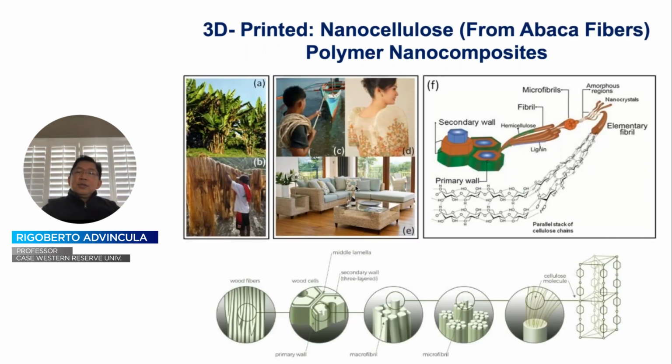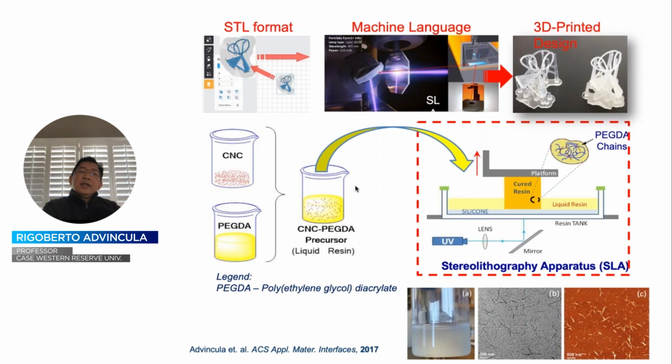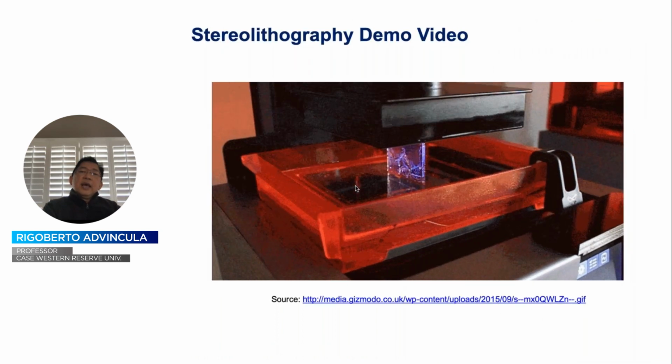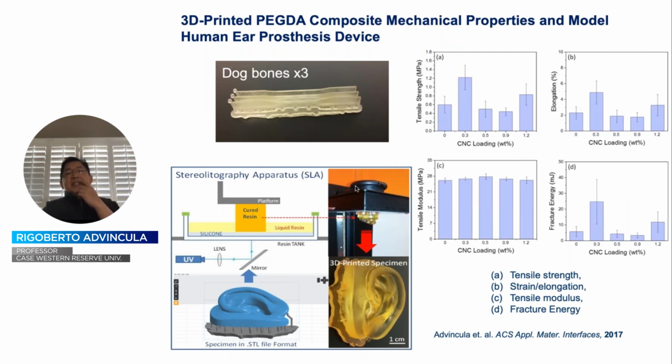Now, let me end by using this last example where we used nanocellulose to incorporate the nanofiller material. Again, in this case, we made our own resin material based on polyethylene glycol diacrylate. The nanocellulose materials are isolated as shown here in the form of whiskers. We mix this with various ratios with the PEGDA resin that contains the photoinitiator and diluent resin, and then 3D printed them.